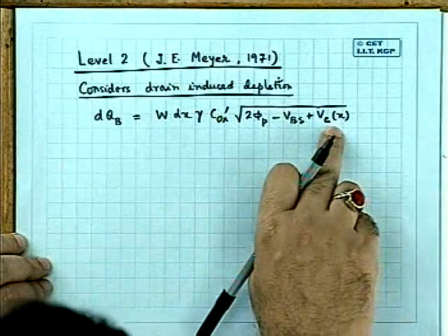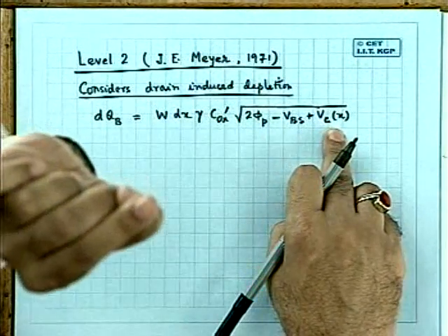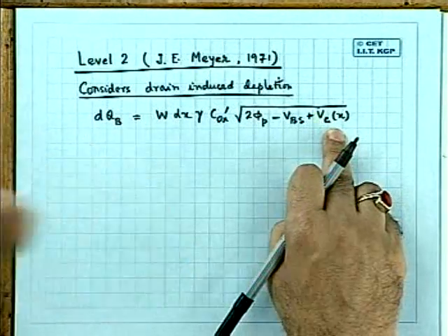Here we have now added that Vcx. Vcx is the potential at the surface due to the current flow, due to the ohmic drop, called channel potential. And I also told that it also takes part in depleting the channel. I told earlier that the channel cannot be depleted beyond phi s equal to twice phi f.